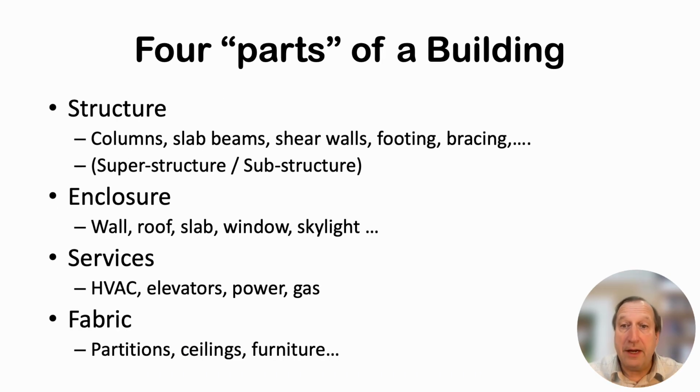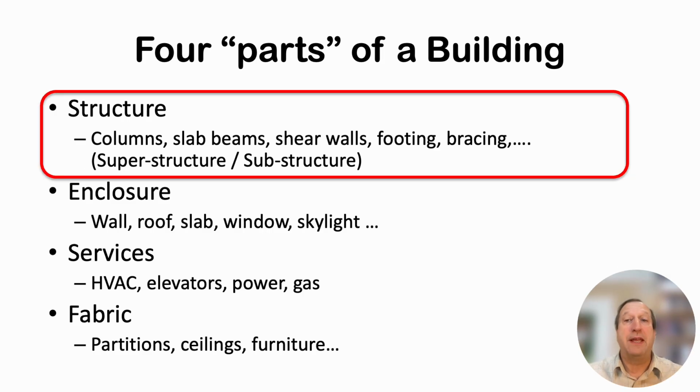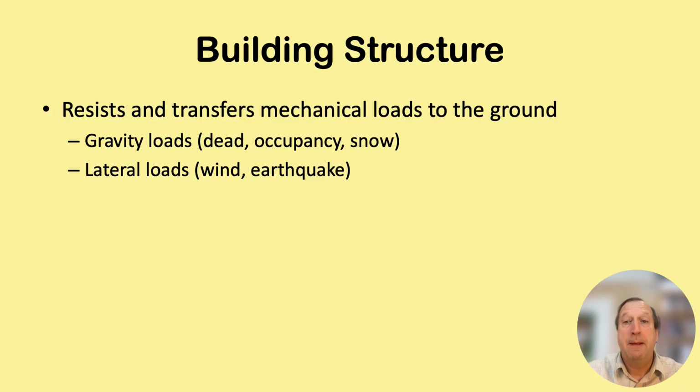So to be clear, the superstructure or structure is going to be the things that we would recognize as columns, slabs, elevator cores, bracing, and so on. And they're not even really the physical component, because what they are is part of the components of the building that transfer loads. So what we mean by that is that they collect and transfer gravity loads and lateral loads primarily.